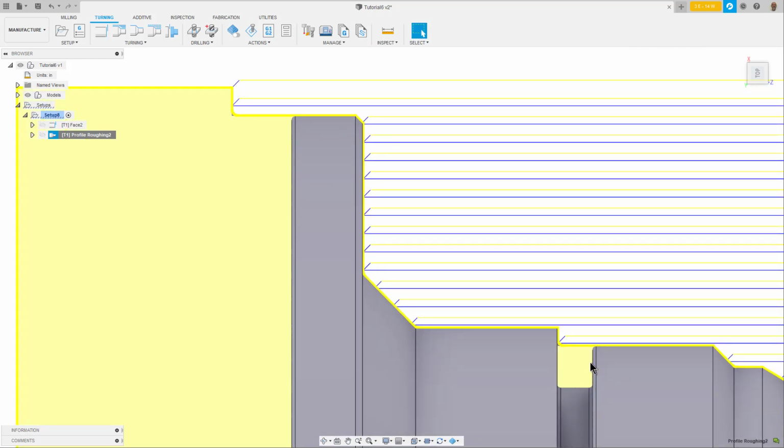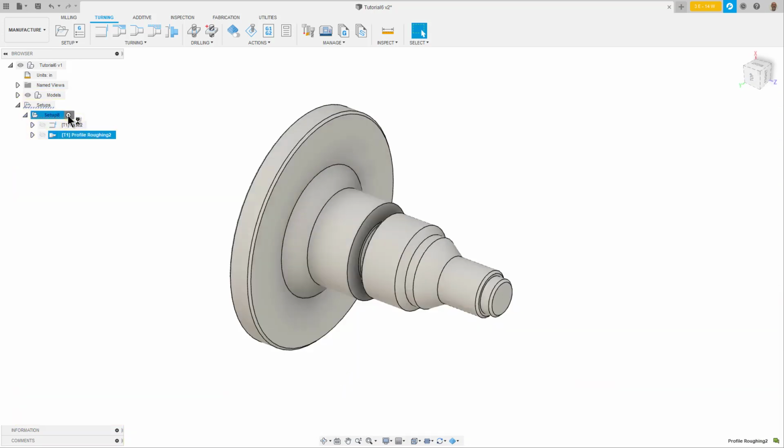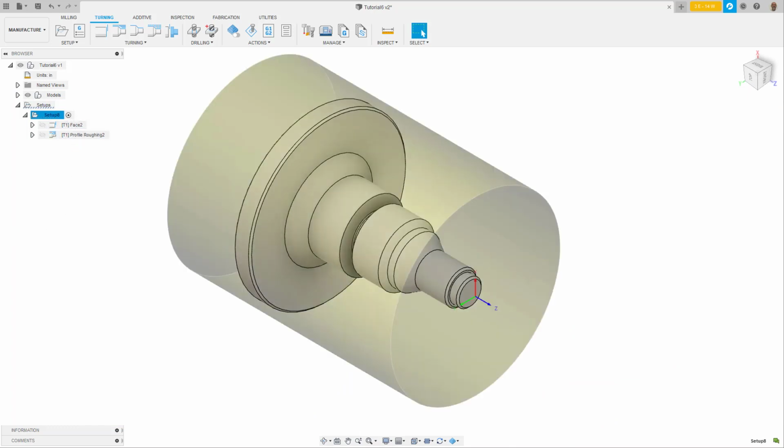In this lesson, we learned about the turning profile roughing toolpath strategy, controlling the cut direction, containing the cutting area, can cycle options, setting the cut step over amount, and setting the stock to leave amount. Press Ctrl+S to save the part, Command-S on the Mac.